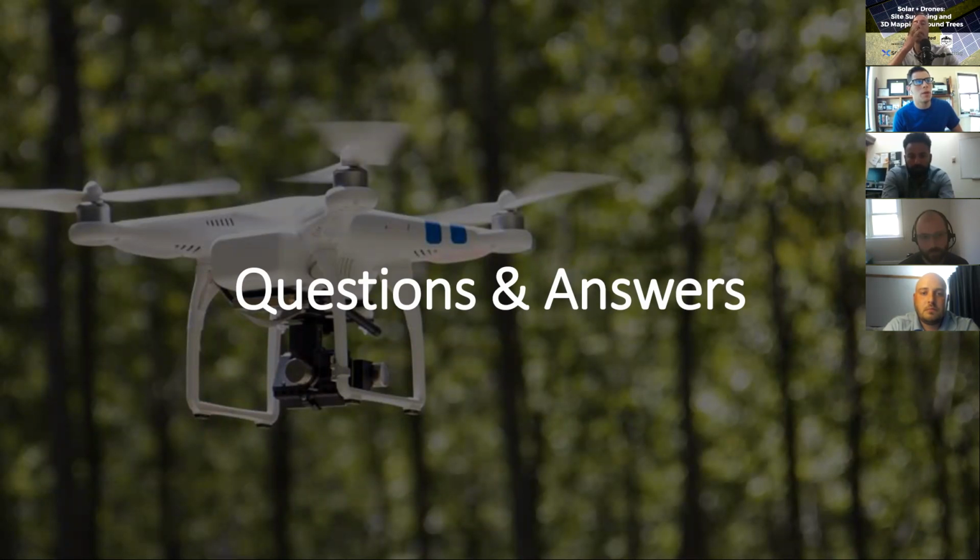I'm going to add one thing from the accuracy side. Photogrammetry right now provides, we say, near perfect accuracy. What that comes down to is roughly 2 to 3 inches across the 3D models, and that's not a Scannfly thing. That's driven by the consumer grade GPS modules in the drones. So when it comes to surveying tree vegetation, when it comes to capturing great accuracy for your solar project, photogrammetry is more than enough in almost every circumstance.